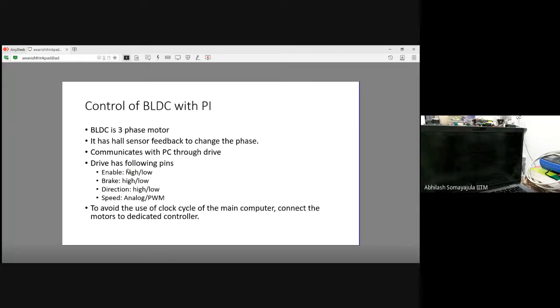For example, as I said, when you are going to buy something, either a sensor or a motor or whatever, you need to first understand what your controller is, what your processor is, what you are using, and what it understands. What protocols are available on that board or controller board, and then accordingly you fetch the motor or the sensor. Like for example, if I go ahead with an RTC, which is a real-time clock, and I do not have I2C communication on my processor board, then I cannot do it.